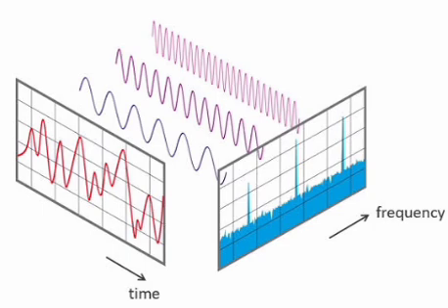Response of an LTI system to a sinusoidal input. Any LTI system does not affect the frequency of the input signal. Only amplitude and phase changes take place. For input A cos(omega t plus theta), the output is A |H(omega naught)| cos(omega t plus theta plus angle of H(omega naught)), where |H(omega naught)| is the magnitude response at omega equal to omega naught, and angle of H(omega) is the phase response at omega equal to omega naught.